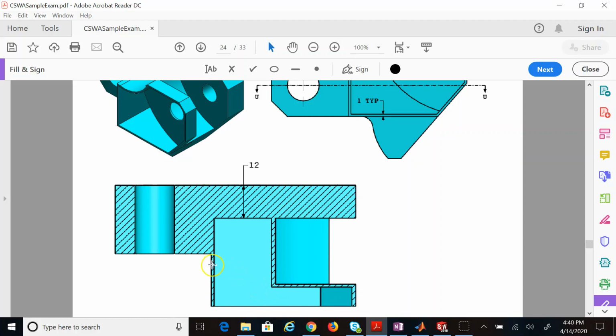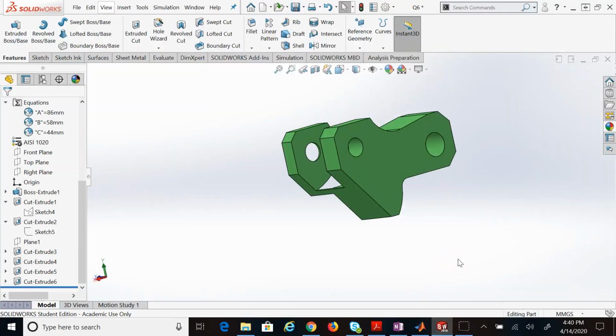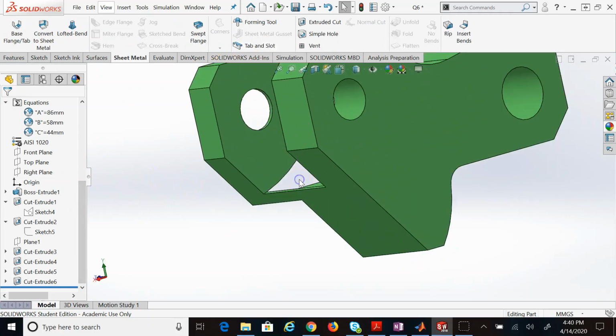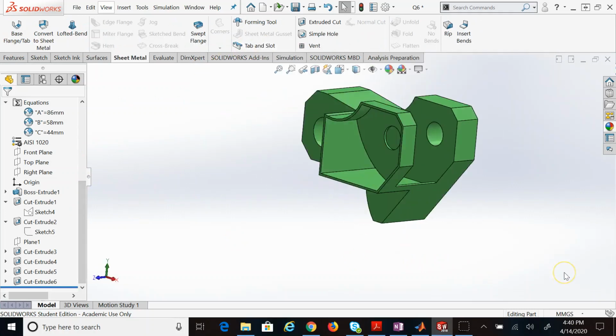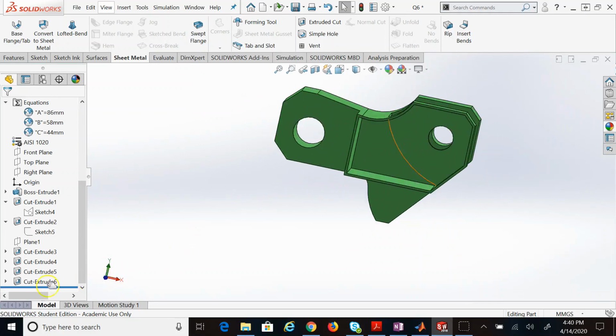So I used the sketch that goes like this, and then the end of it was this point and not this one. So it is cutting all the way from here to the back, and it did not give me this small ridge here and here, so that's why you see this back wall. You see this open space here, which is quite weird, right? It shouldn't be like that. So what should I do? I need to modify that sketch.